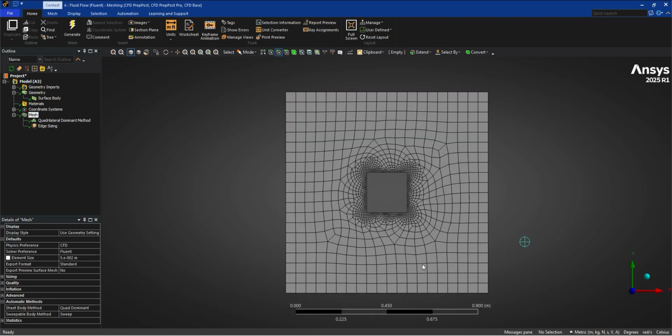Okay, there we go. So this is not the best mesh we can use, and this is happening because we are using a structured mesh, and we don't have a good growth ratio here, and it's a small geometry. All of these we can do. So there are a couple of things we can do. This is a problematic mesh. We don't want to use this in our analysis. There are a couple of things we can do.